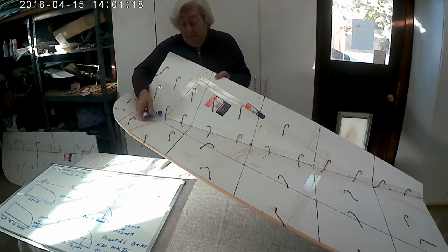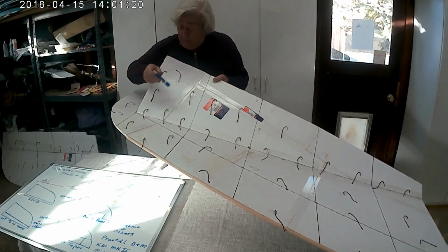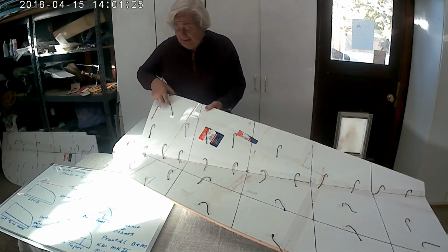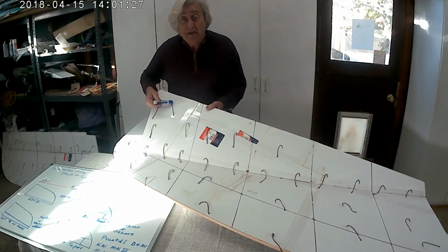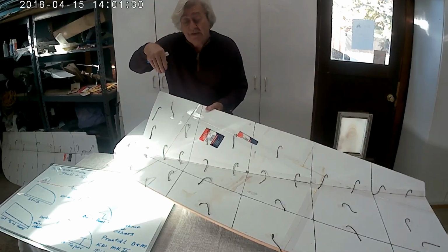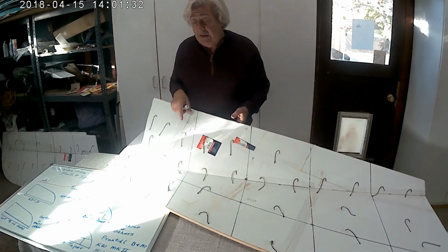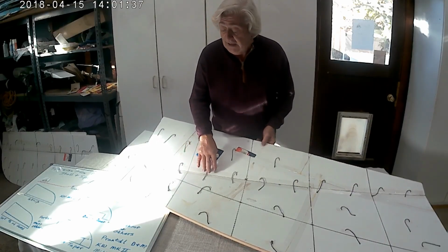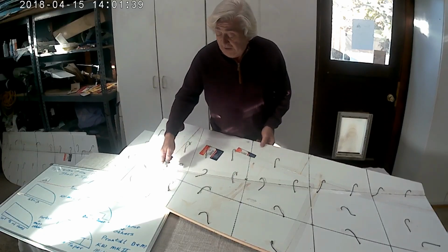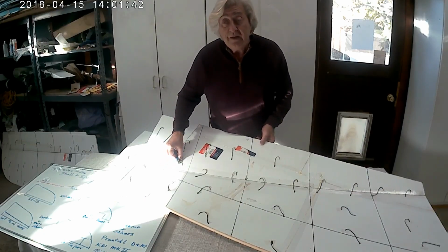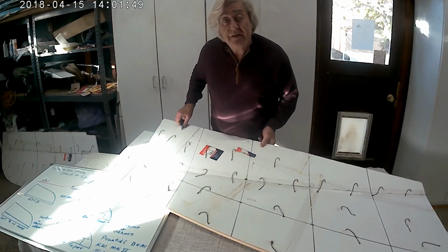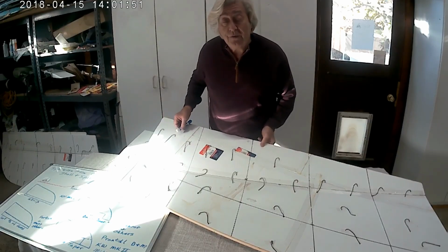Well, if we need momentum to get up this hill, better start here. If we put a little strip elevon back here, there's no momentum left to get up over the hill of the control surface deflected up. This is a situation of positioning or shaping the elevon such that the hinge line, where the air molecules have to start going uphill, is where the air molecules are moving the fastest and have the highest momentum, and hence the highest probability of getting to the trailing edge without separating or going spanwise.